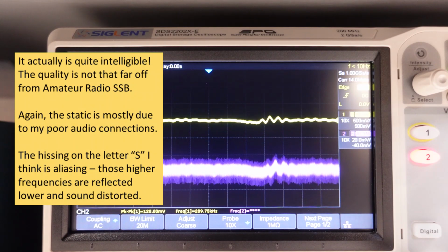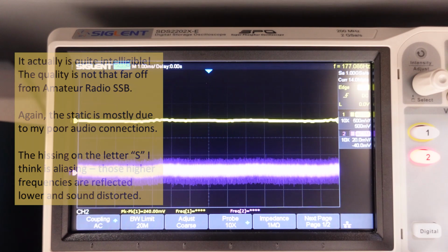But the bigger issue is the sampling rate of the ADC. Now, I haven't settled on one yet, but I know it's not going to be anywhere near 40 kHz, which is the absolute minimum needed to avoid aliasing issues. I'm really tempted at this point in this project to continue tinkering with those circuits in the software to optimize the sound quality. For sure, those were just first pass attempts to prove that it would even work.